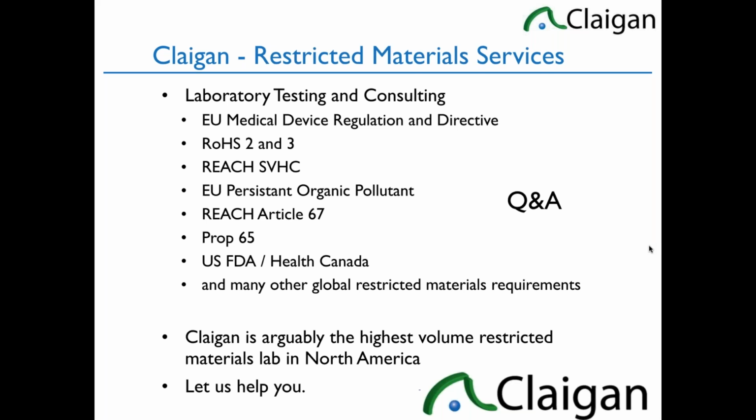The metals are easier to screen using XRF or ICP. Beryllium is pretty much only ICP because of its low molecular weight. But there are a number of techniques, and a lot of advanced techniques for each one. Endocrine disruptors are handled the same way as REACH SVHC: what materials are reasonably likely to contain endocrine disruptors or CMRs? In our case, we do a tremendous amount of it, so we have a fairly significant knowledge base, both in engineering evaluation and in screening and testing techniques. It's pretty advanced here. This is a really specialized field. One of the reasons testing a representative product is really useful is that you learn a lot.